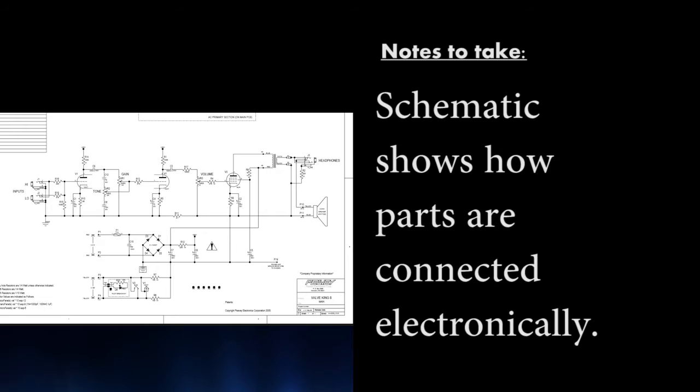So nowadays it's a lot harder to get your hands on service manuals with assembly drawings and schematics like this, but they're really helpful when troubleshooting damaged equipment, because you can say, okay, here's the power supply and the 12 volts I need this thing to work is supposed to come in at this part of the circuit, and then you can take your test tool and see if 12 volts is actually on that part of the circuit, and if it's not, then you've got a power supply problem, and so on and so forth. But you're going to have to really work to get these documents anymore.